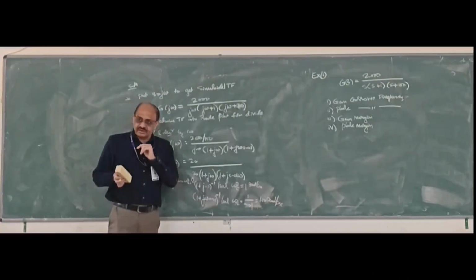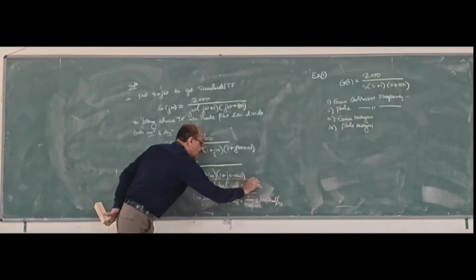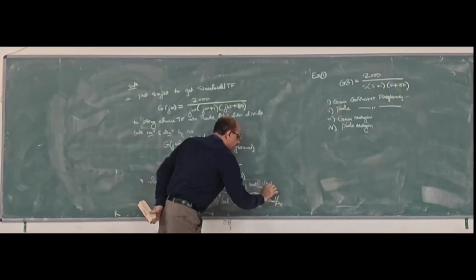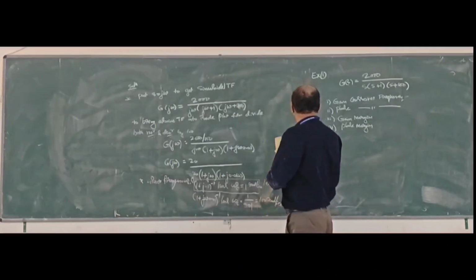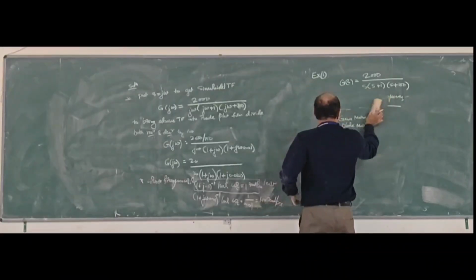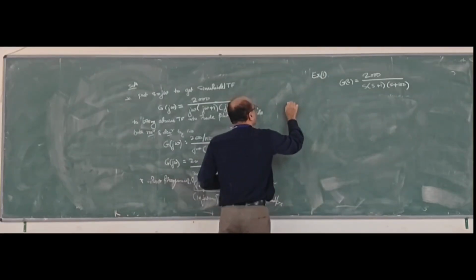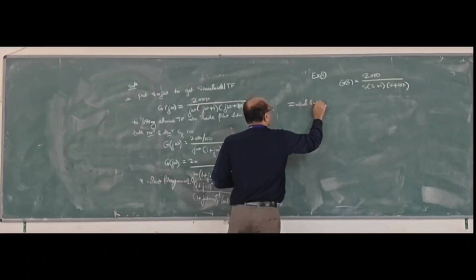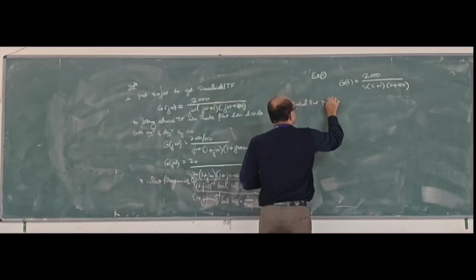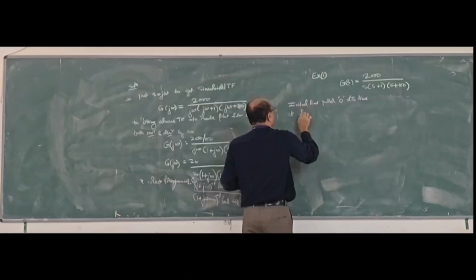The starting frequency must be lesser than the least corner frequency, so mark this one. And the initial line passes the 0 dB line at a frequency.